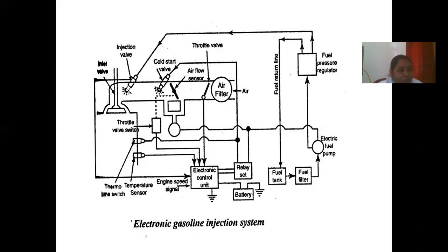The air flow meter consists of a rectangular plate which turns in a rectangular shaped channel to a defined angular position depending on the pressure from the flowing air. It returns to its original position during normal condition by using a spiral coil spring.